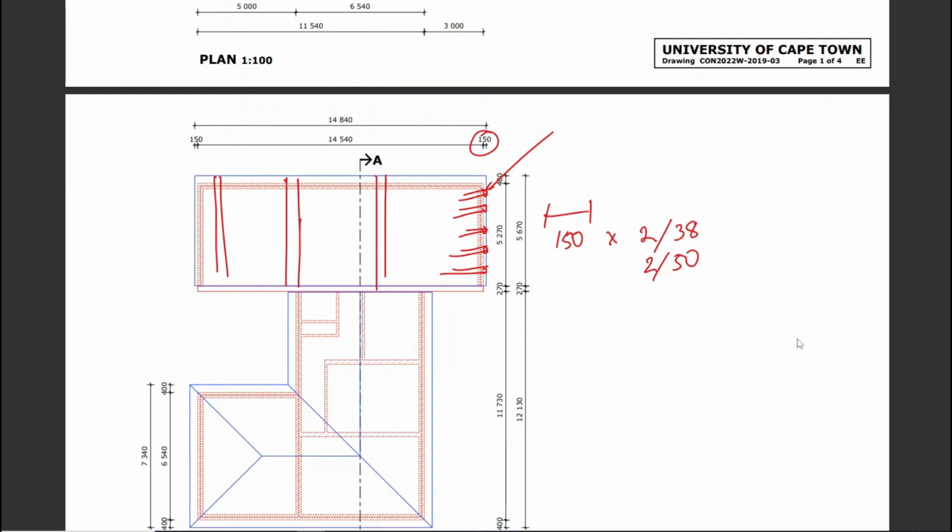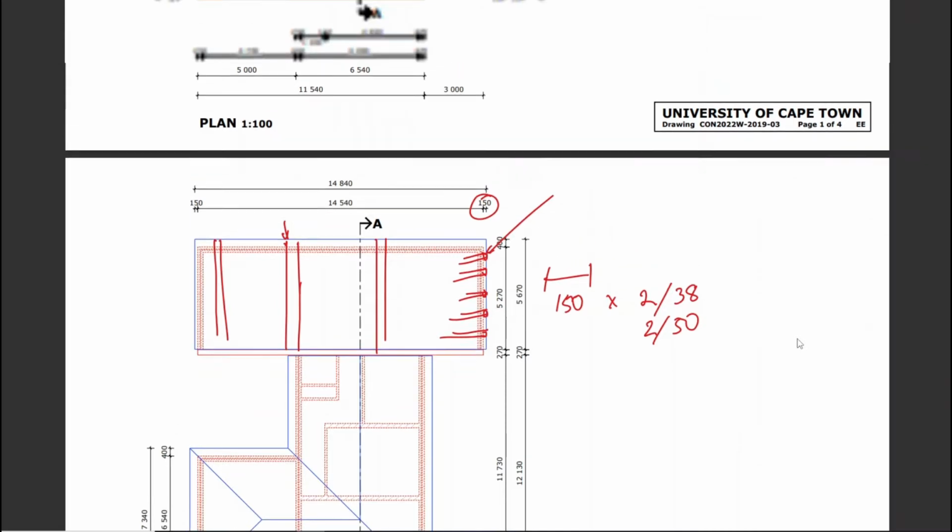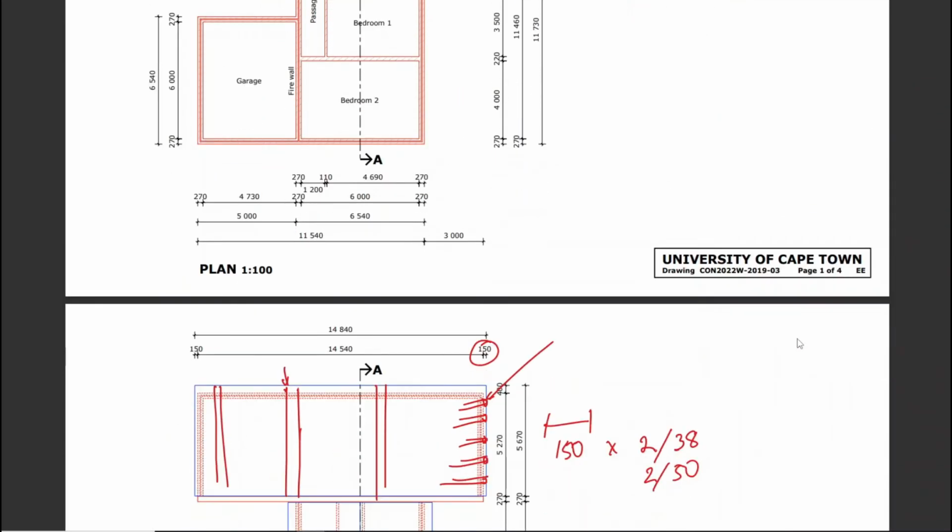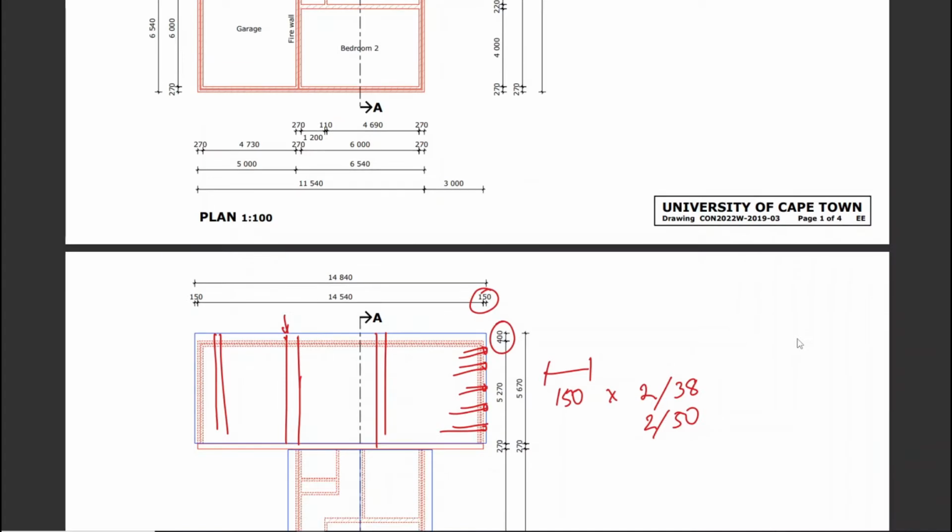Now, I don't think there's any scenario where you, yeah, I guess there could be a scenario where your purlins are on slope, but in your rafter ends on this side, this case, it needs a factor. So even though its overhang is 400, it's given, this 400 here, you're going to have to convert to an on-slope dimension to get what this actual exposed piece of timber is. So when timber is running up the slope, you're going to need a factor. When it's running sort of along the slope, there's no factor involved.